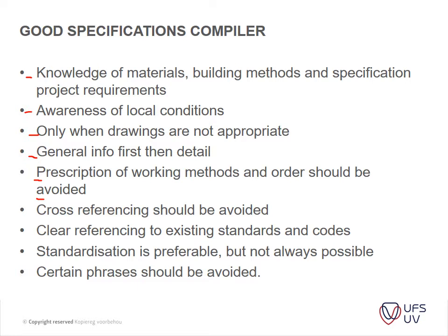Cross-referencing should be avoided, and especially in our computer age, it's something that crops up quite often. Whenever you're duplicating certain sections in a drawing, it does pop up quite a lot that you maybe forget a construction line, or the lines may have a different font setting, especially if you're working from old drawings to new drawings and the line settings aren't exactly the same.